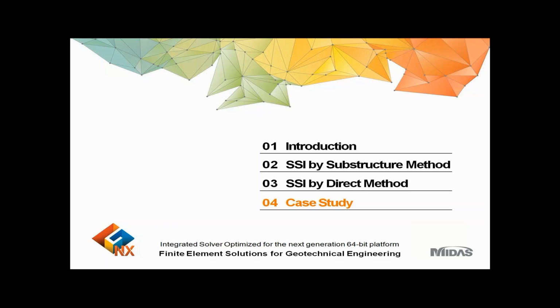From the geotechnical viewpoint, the results of settlements, total and differential, the distribution of loads and bending moments in the piles, the interaction between the raft and the soil, which is the pile-raft hypothesis, and the interaction between the piles, which is the group effect, are very important topics that can only be achieved with some accuracy when using 3D numerical modeling. So along with a platform that enables this modeling, the soil properties might be modeled with the use of soil constitutive models, and MIDAS GTS NX allows this analysis to be done with all those prerequisites.